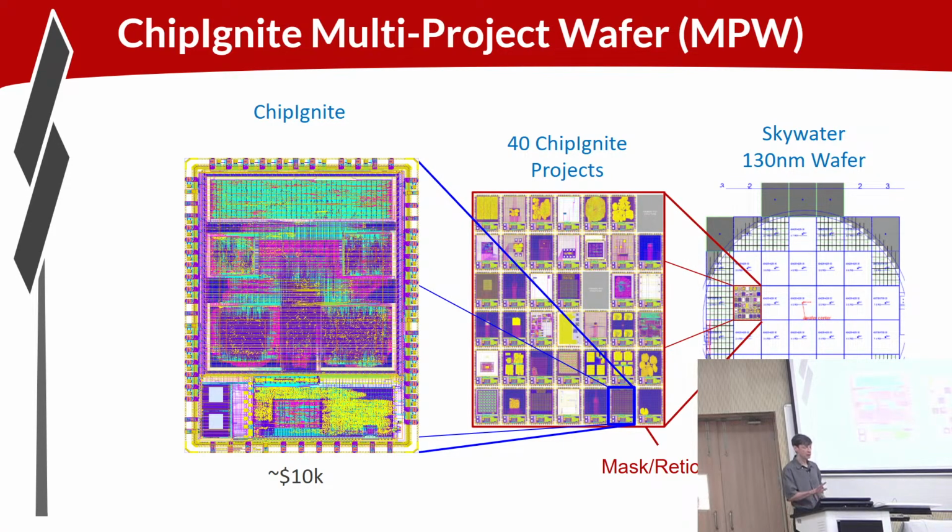So this is the picture for Chip Ignite from eFabless. They give you this framework to work in. Down here in Caravel, this is a control processor to help bring up your hardware, whatever it may be. And they provide this multi-project wafer framework. So they combine your project with 39 other projects, put that onto a mask, and stamp it out on the wafer.